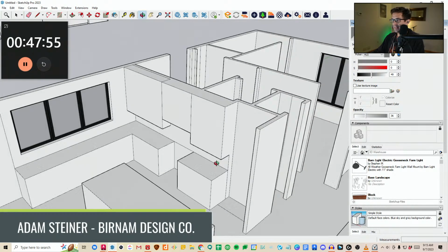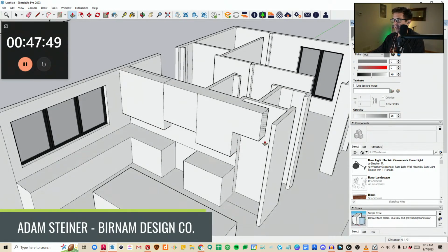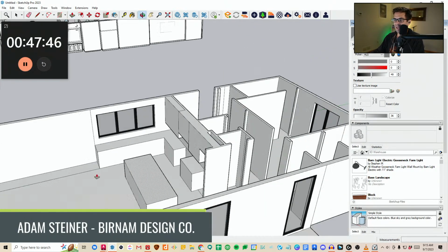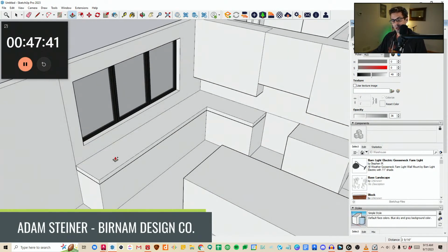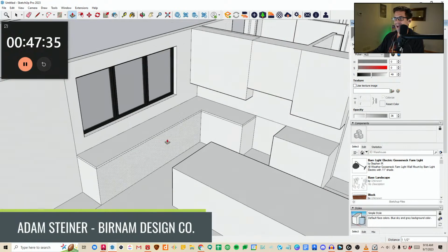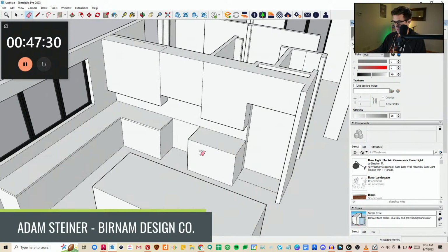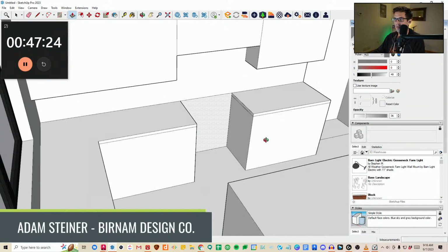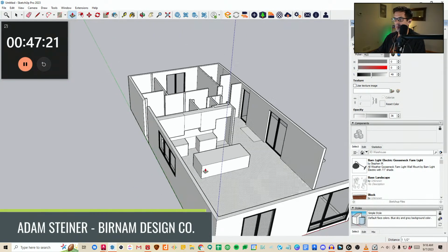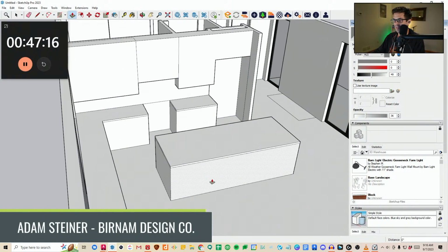Okay. Delete these extras. There's a line there separating cabinetry and wall. And you'll have a cabinet above the fridge. Alright, yeah, just simple blocking out here. But what I'm going to do then, using push-pull, bump down 1.5 inches for our countertops. Same thing here, P, and then hit Control, which creates a new face as you're pushing, instead of pushing the original face. So hit Control, see that little plus there? Now I've got new faces.